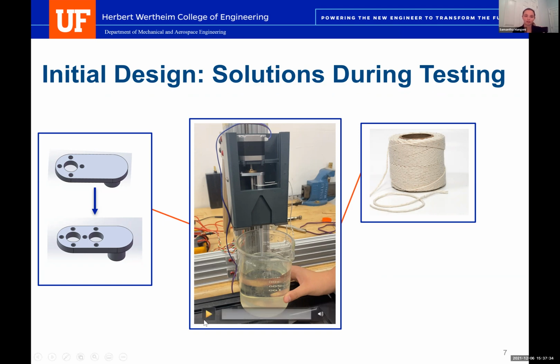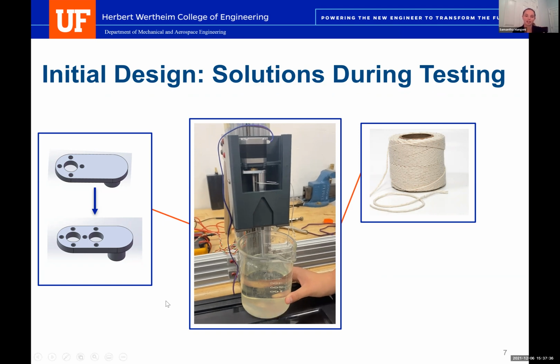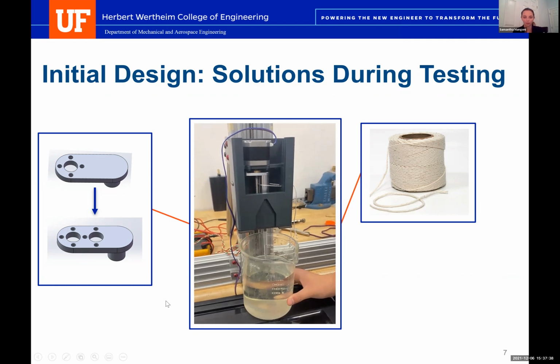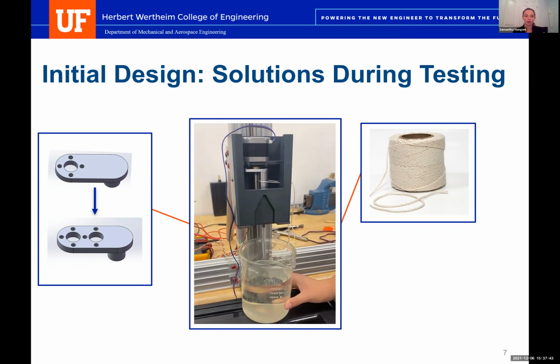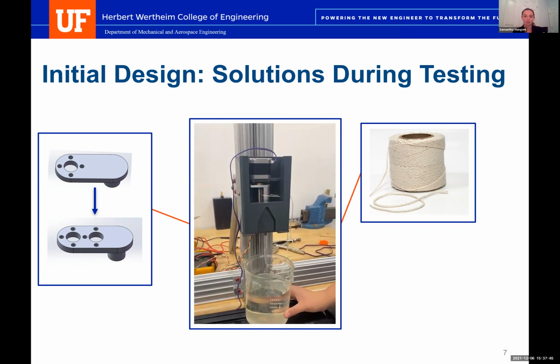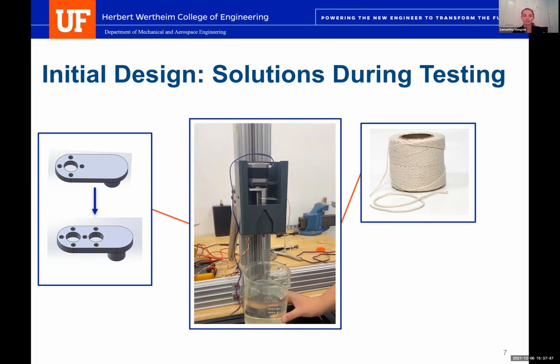The string was effective in counteracting that moment, and we were able to move the cylinder up and down during testing. But this really paved the way for our final design, where we decided to make the lead screw in line with the cylinder. Next slide.